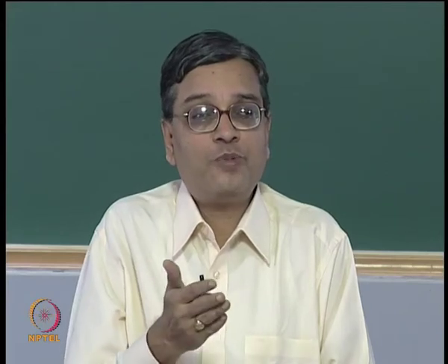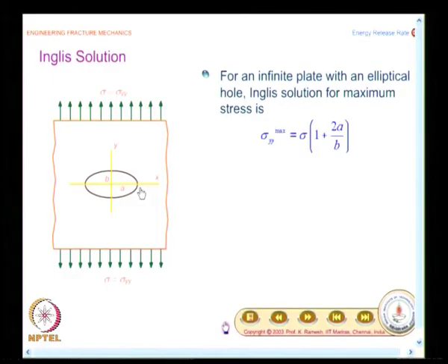For many problems, if you look at the definition of stress concentration factor from theory of elasticity, it says the maximum stress divided by far field stress. That would be greater than 3 for many finite bodies. It would approach something like a factor of 9 or so, but it would not increase beyond that. For many of the common design problems, that is how people have looked at the stress concentration factor. On the other hand, when you look at the case of an elliptical hole, Inglis alerted that when b tends to 0, the stresses go to infinity.